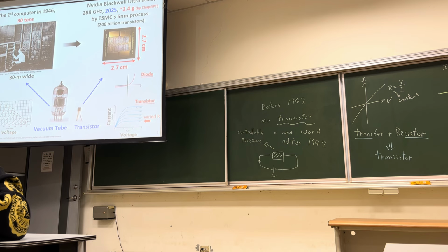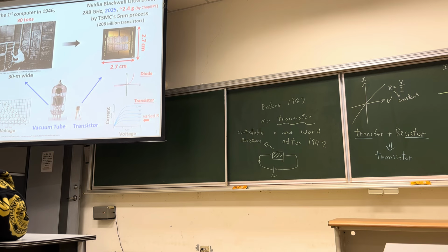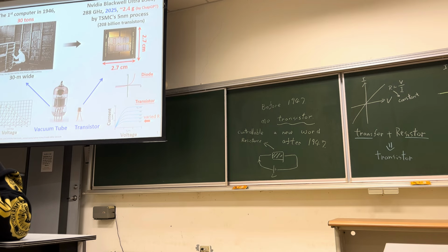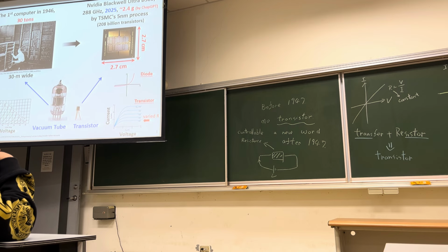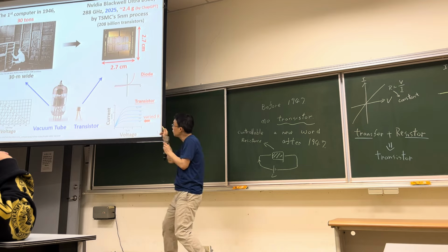What do you mean by easily controlled? It means the slope of this IV curve is fixed at a certain range of voltage, not changing all the time. It cannot be too sensitive, otherwise your circuit will not be stable. It got to be changeable, but in a stable way. 它是可以控制的，可是不能太敏感。这个就太敏感，因为它每一段的斜率都不一样，斜率就是它的电阻，对不对？斜率就是 I 跟 V 的 ratio，对不对？Okay, so this is not the ideal transistor. Okay, ideal transistor will give you the IV curve like this.